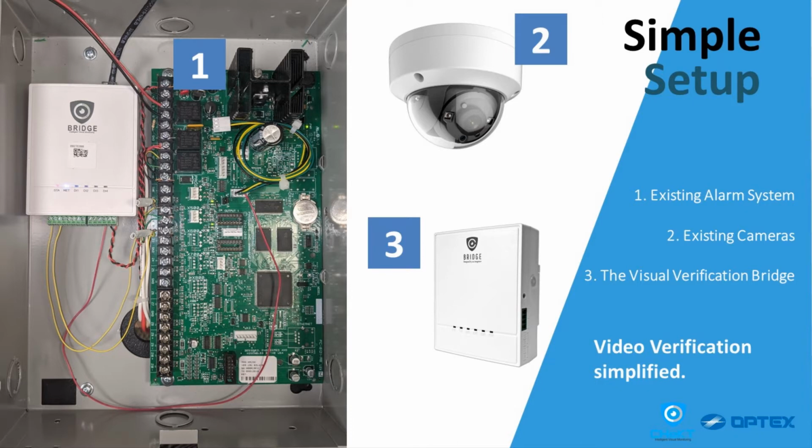And so what you can see is these 2 yellow wires are supervising zones 1 and 2 on that intrusion system. And the green wire there is getting arming and disarming status information from the intrusion system. And then the red and the black are just power. So real simple setup. So you can take existing sites or go in on new sites and take that intrusion system, IP cameras or HD over coax cameras, and this bridge, and you're tying everything together.